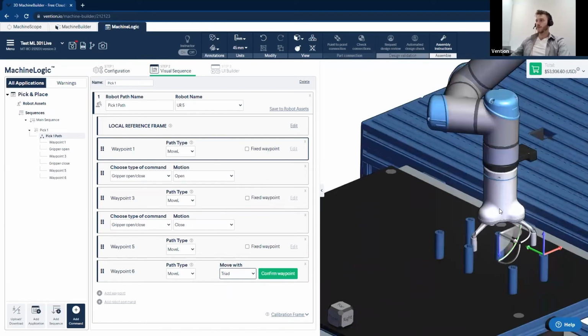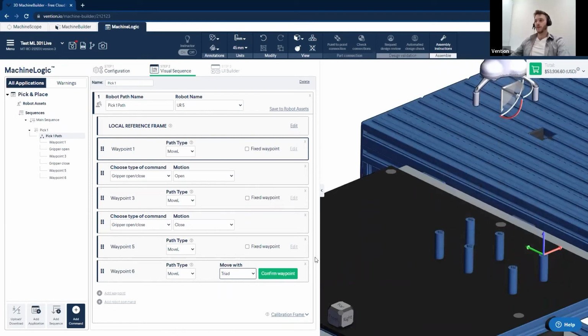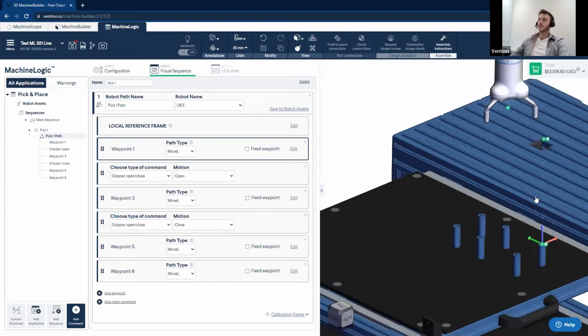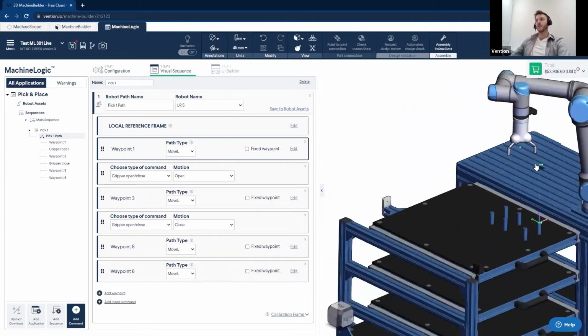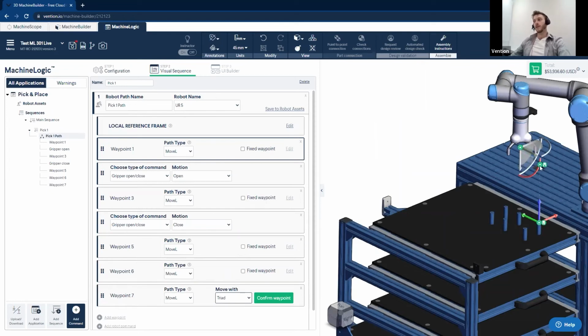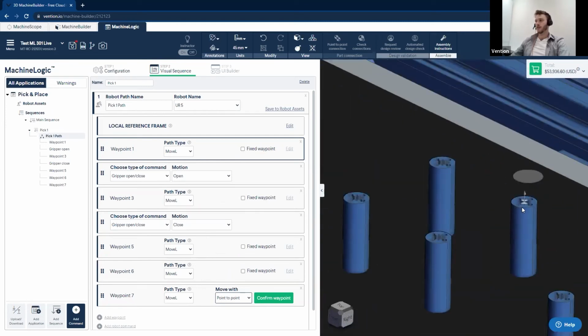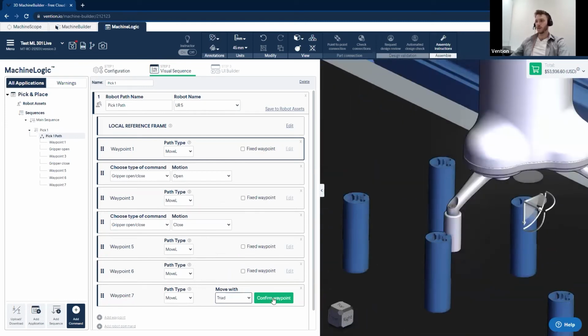Again, drag it up. So there are 2 different options. You can drag it up using the triad that I've seen here, but you will sometimes end up with the robot at a different height from the original cruising altitude. So you can also go into the jogger at the first point to see what its Y position is. In my case, just for ease of use, I'll continue using the triad and the point-to-point connection tool.